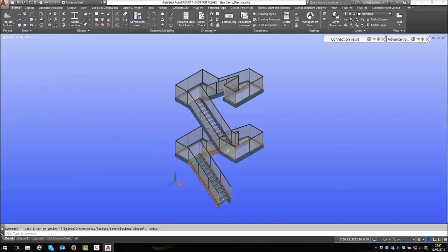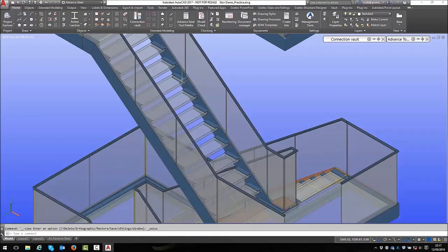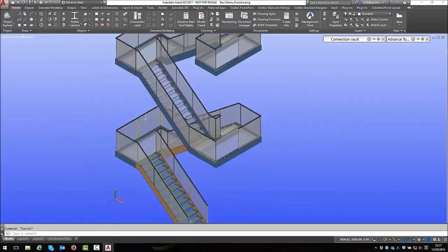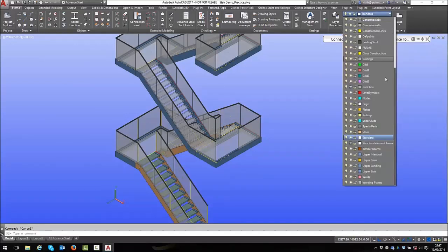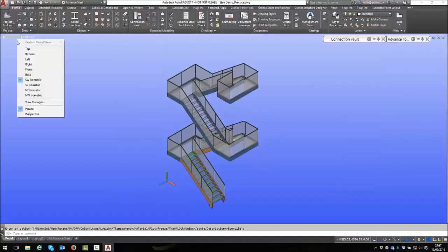I've showed you how to create the glass treads, how to use parts, which I've created in a separate model, copy and paste those in. How to create stringers is use the sections. Hand railing, use the sections again. Bring it all together. I use materials, which gave me the glass effect on the panels. Let's turn off our construction lines. Let's turn off our glass construction lines. There's the finished item. Hope that's been informative.